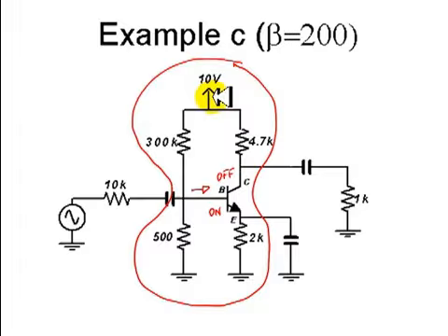How does it do it? Well, this voltage divider will set a voltage here at the base that will push a positive current into the base, ensuring that the BE junction is on. At the same time, this voltage source will pull up the voltage of C above B to ensure that this junction is off.